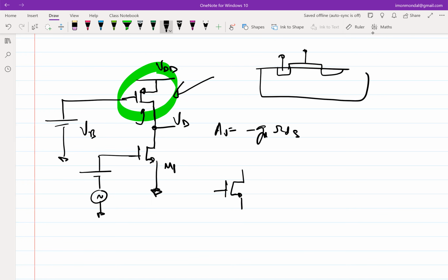So is this an NMOS or PMOS? You tell me. PMOS, right? PMOS. Okay, I have reversed it, sorry, thank you. What I wanted to say was this. Yeah, the problem here is that the source should be connected to the minimum potential.